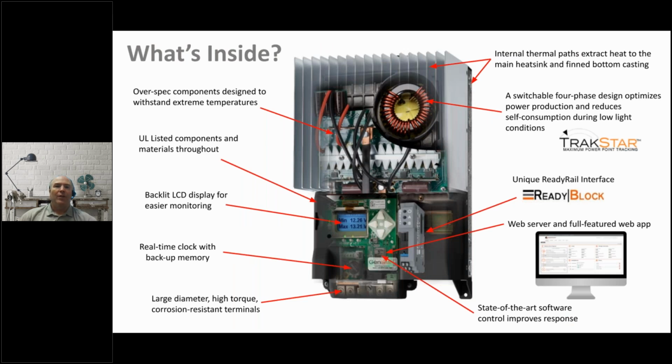And we've included a cutout view of our newest controller. This is our Genstar MPPT controller. We've recorded webinars on our website about this new product, but I just wanted to attach this slide to your handouts so you can get acquainted with the Genstar MPPT, which comes in 60, 80, and 100 amp models with a maximum VOC rating of 200 volts. And this can charge 12, 24, and 48 volt batteries.